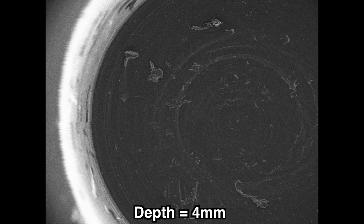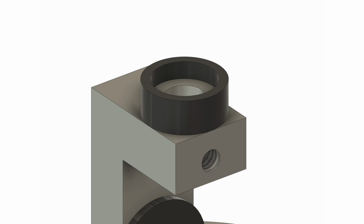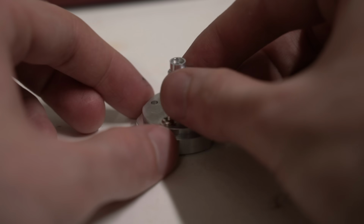As we increase the depth to 4 millimeters, you can see a noticeable improvement, which gets even stronger at 8 millimeters. And at 16 millimeters, the surface inside is basically pitch black, indicating that virtually zero electrons are reaching the detector. So this data tells us that our existing shield is definitely not tall enough. The problem is, our current design is already as tall as it can be without risking damage to the SEM. Are we doomed? Well, not quite.